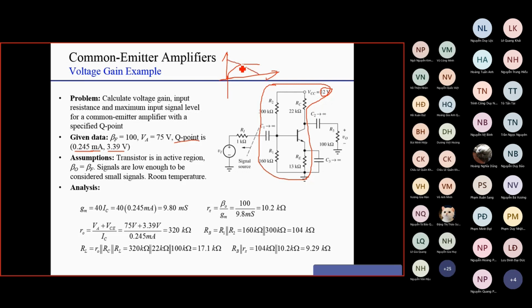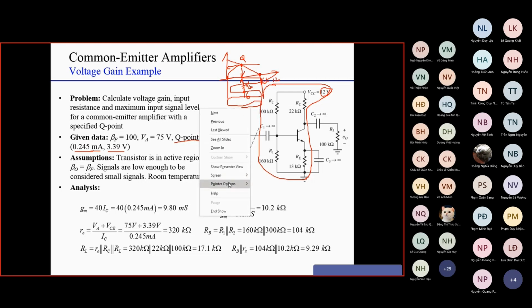The output characteristic curve is here. The optimum working point for the transistor is the midpoint, in the intersection with the x-axis here, which is VCC, and VCEQ must be half of VCC. That means if VCC is 12, the optimum VCE is 6. Here it is not really optimal. We will see about that later. If the Q point is not at the midpoint, the maximum amplitude of the output signal is limited, but we will consider that later.